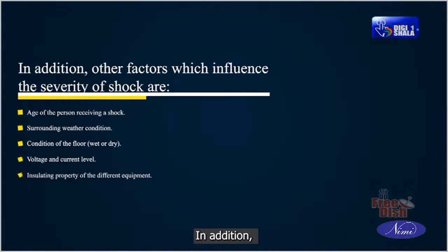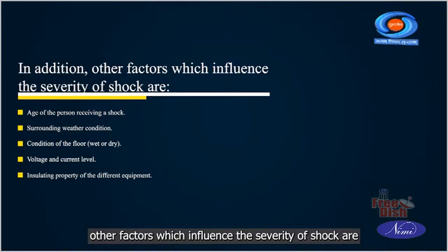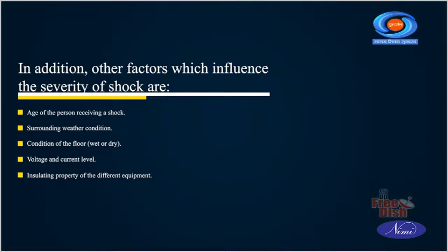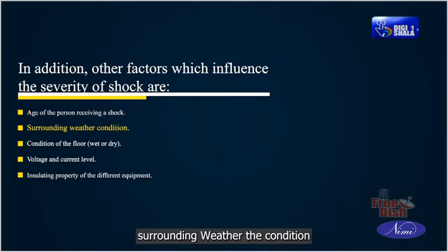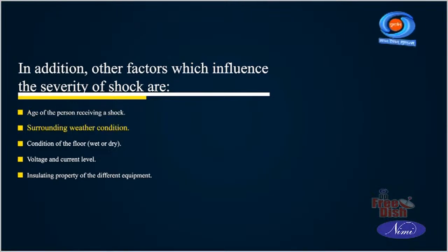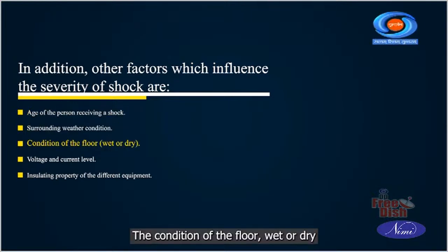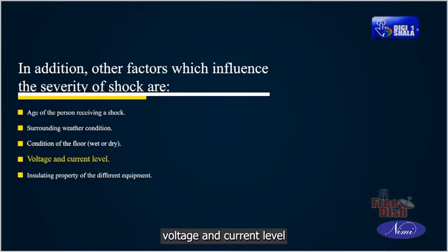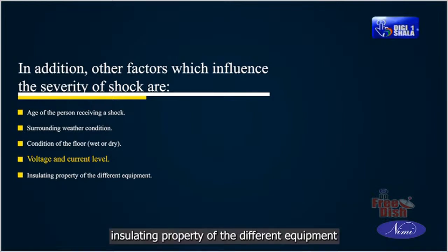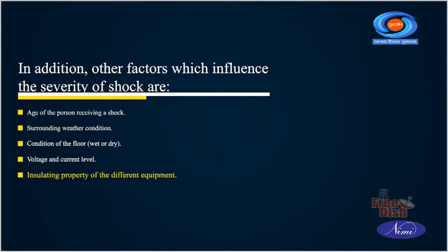In addition, other factors which influence the severity of shock are age of the person receiving a shock, surrounding weather condition, condition of the floor, wet or dry, voltage and current level, insulating property of the different equipment.